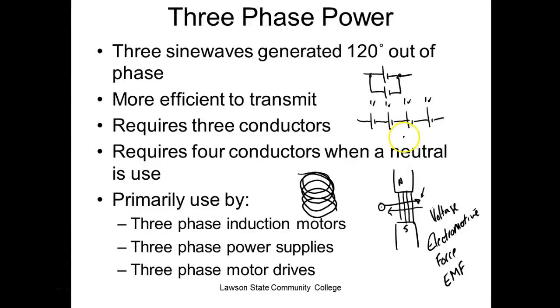So in series, they do what? They add. So what adds up here? The voltage adds. Yeah, up here the current adds. So when you get your remote, some batteries in series, some of them parallel. The ones hooked in series, we use that to get a higher voltage. The one hooked in parallel, we get more current, right? You understand that? Everybody okay so far?